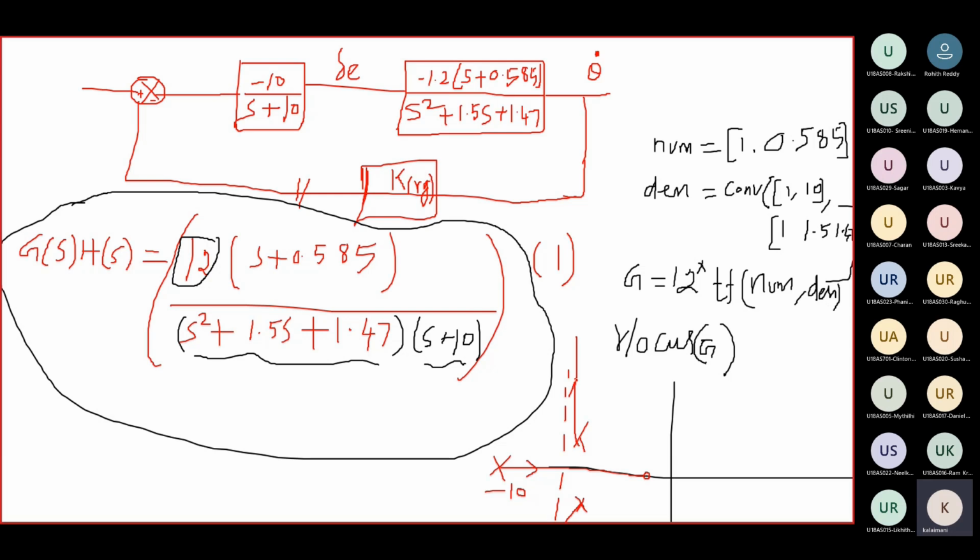These root locus branches start from poles and follow the path of the 90 degree asymptotes. They will meet at zeros at infinity. In the same way, these root locus branches start from these poles and follow the minus 90 degree asymptotes. They will meet at zeros at infinity. We try to sketch this root locus in MATLAB, and we see.